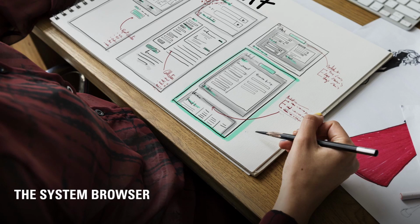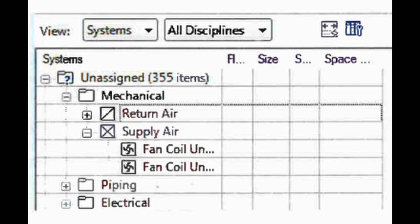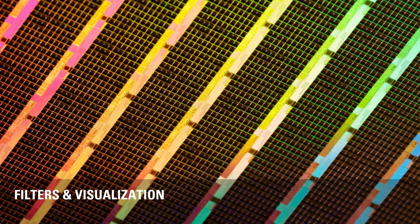The System Browser. The System Browser is located under the Analyze tab or the View tab in full Revit installations. It displays every system in a hierarchical structure, by discipline, by system, or by zone. The browser is fully bi-directional, meaning changes you make in the browser affect the model, and selections in the model highlight items in the browser. You can use it to find unassigned elements, diagnose gaps and missing components, inspect flows and loads, check system continuity, filter systems by discipline or name, and of course you can launch it instantly using the keyboard shortcut F9.